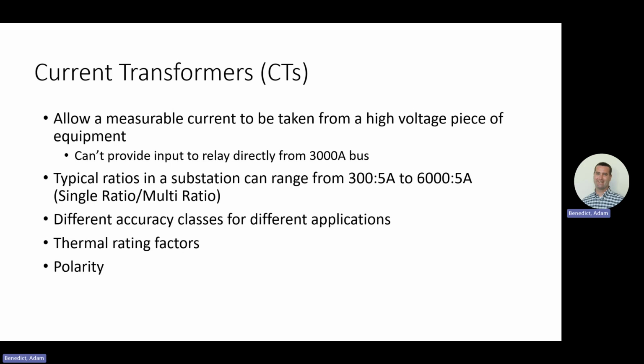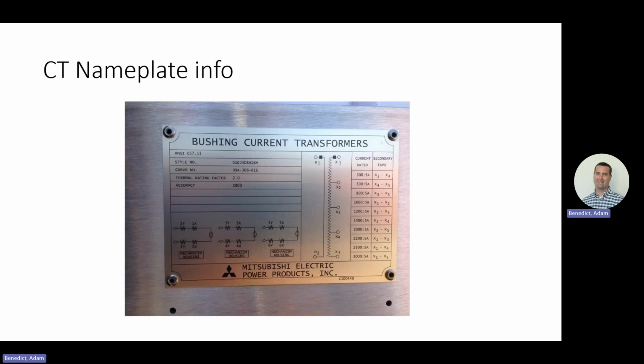This is where you would work with your settings engineer to see where the saturation level is and make sure you're specifying the right CT, whether it's C400, C800, C1200, and then polarity markings. And I didn't put them in here because I know that's taught in AC and some of your other classes, but just know that that's another one that gets screwed up commonly.